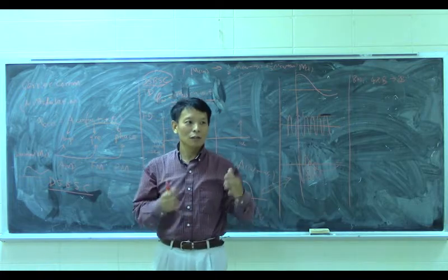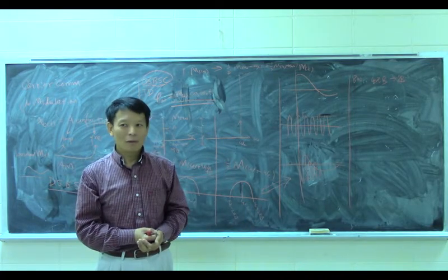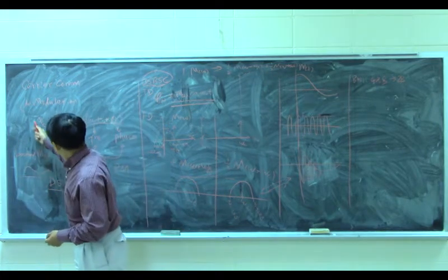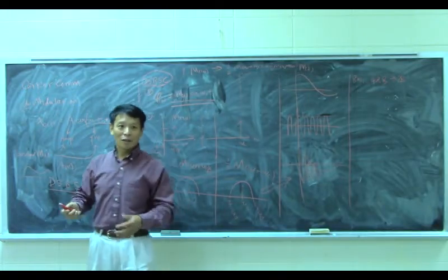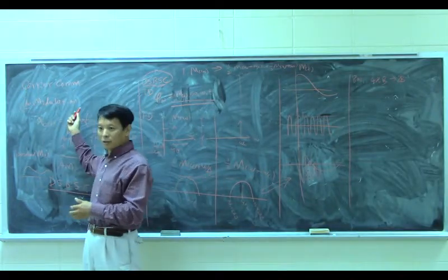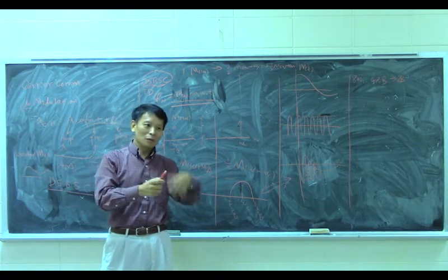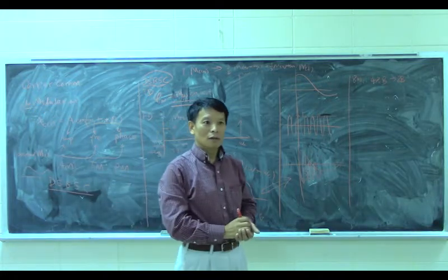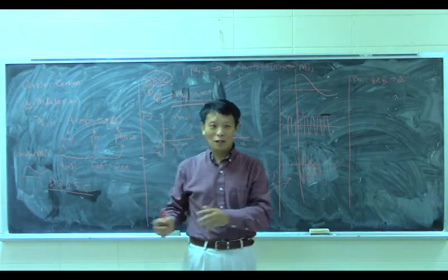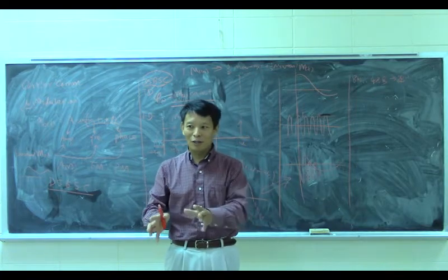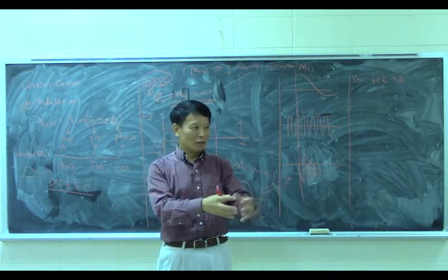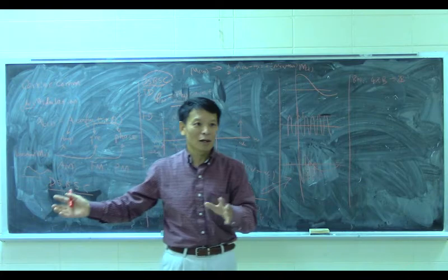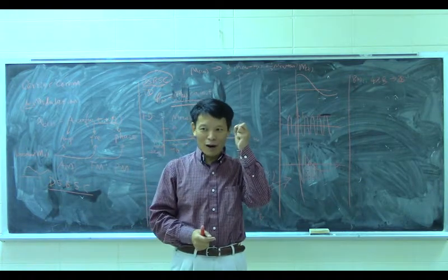That process is called demodulation. From transmitter to receiver, that is called modulation. Now, at the receiver, you want to get the original baseband signal. This is called demodulation. Combined together, they are called a modem. So at home you have a modem that does the modulation and demodulation process. These two can combine together, and actually these two are the same thing. There's only one little difference.